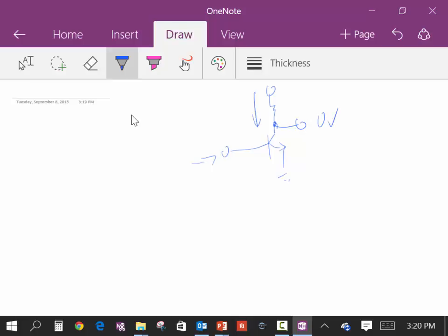If we turn the transistor off, we get no current through here, and we're going to get VCC. When it's turned on completely, that's considered saturation. If it's not turned on at all, that's considered cutoff. Those are the only two modes in which we operate transistors in digital electronics. They're either on or off.